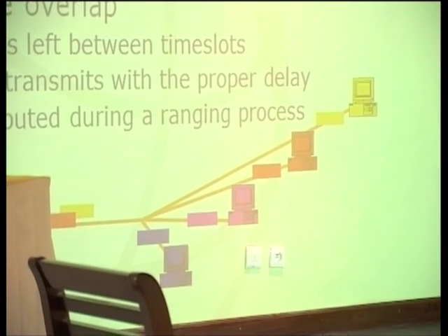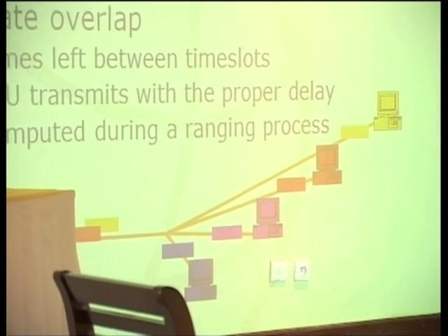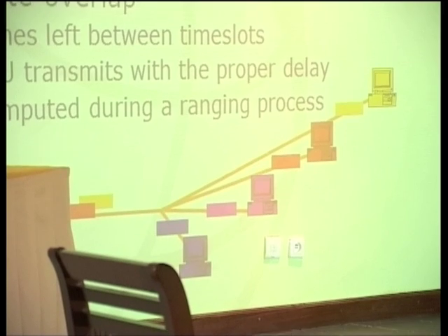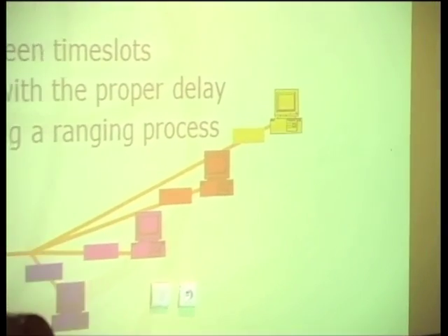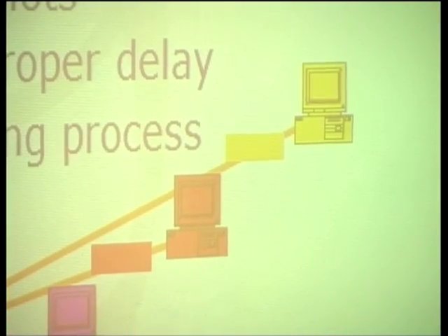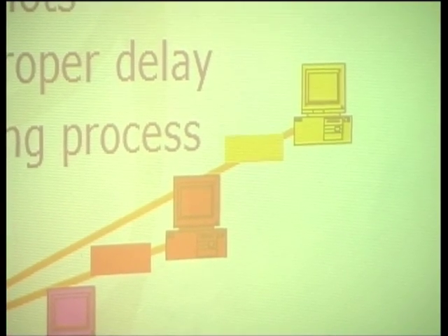I simply mean that we are commissioning the system and we are going to put an ONU into operation. We connect the fiber to the ONU, we power on the ONU, and just after we will have an exchange of information between the ONU and the OLT.